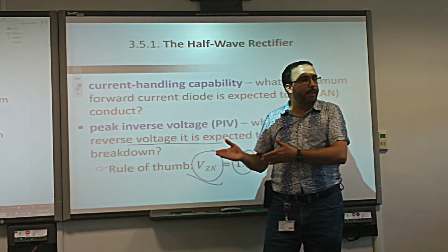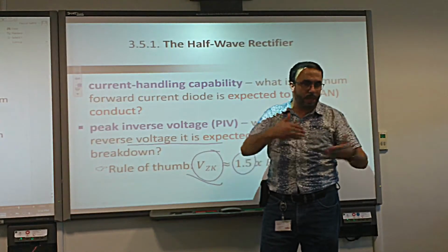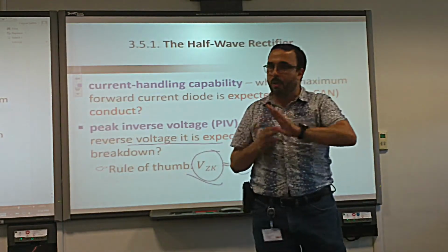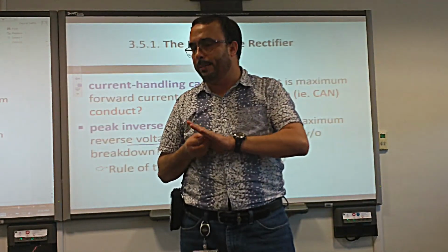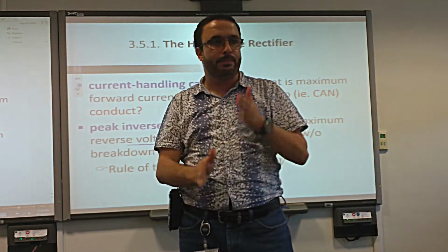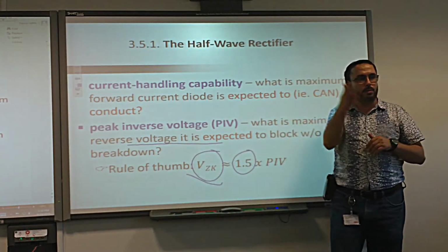Why? Because the rectifier should not have any current in the breakdown. It should not have any current in the reverse, it should be only in the reverse, never in the breakdown. Never. If I reach the breakdown in my rectifier, I have no rectifier. I will tell you, go study something else.